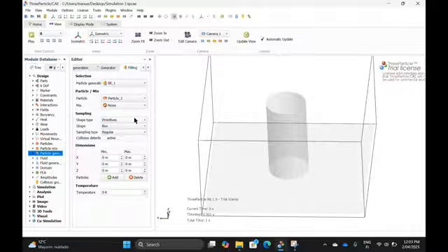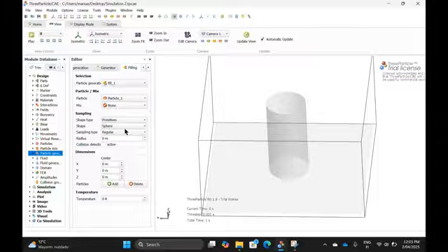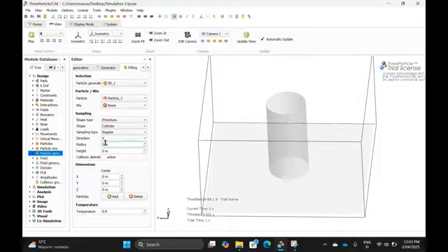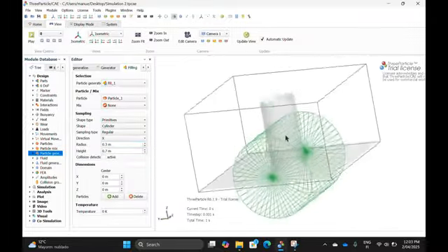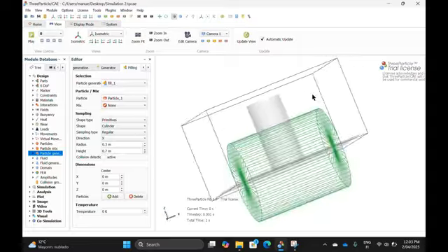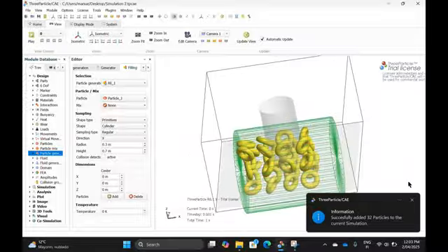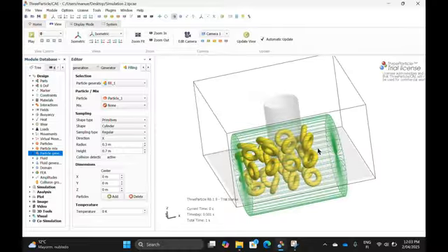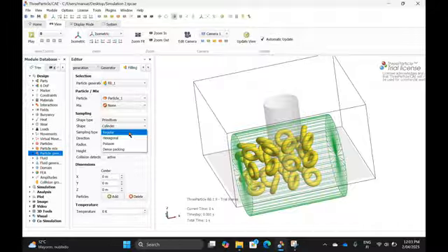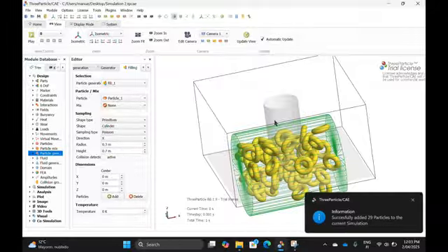We want to fill a sphere with a radius of, or a cylinder with a radius of a certain size and a height of a certain size. Now there is a volume defined here, you can see that already, and that volume will be filled with particles. You can already try that if you click on add. And you see that volume is more or less filled with donuts. We don't want to fill it regularly, we want to fill that in a Poisson manner, so randomly distribute the donuts inside of this volume.